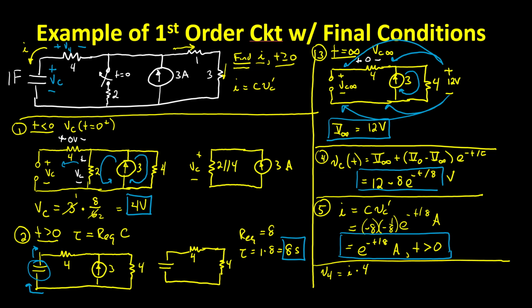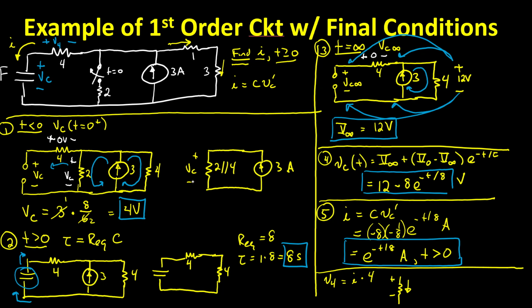And that would be almost correct, except realize that the formula for Ohm's law assumes a polarity. It assumes that current is defined entering the more positive and leaving the more negative. But up here, we've defined the I as entering the more negative and leaving the more positive. And since that's opposite of the way we defined it in the upper left, we have to add a minus sign to correct for it.